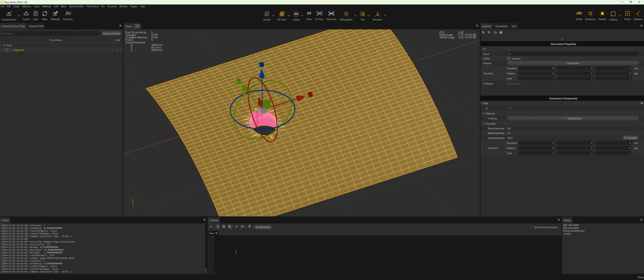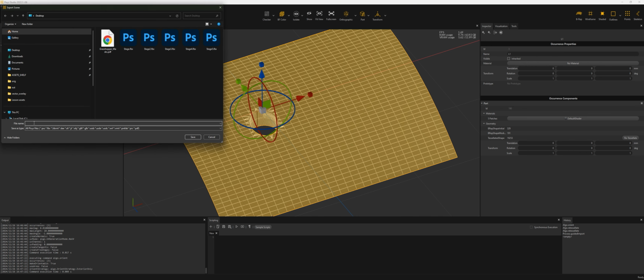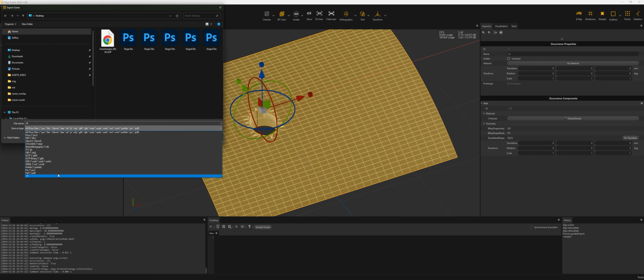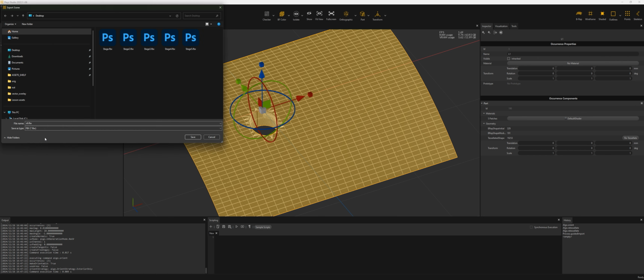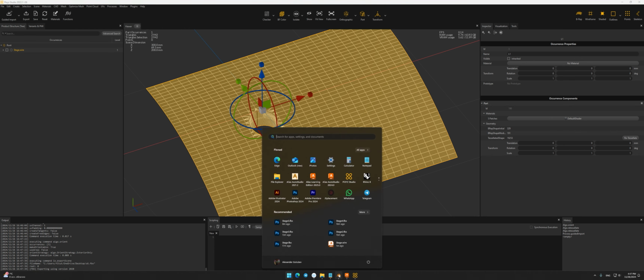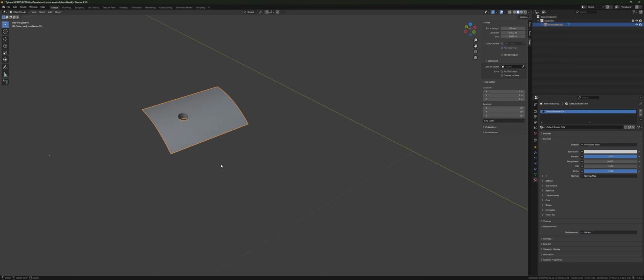Now, when we're done, first of all, I'm going to see that my normals are wrong. So let me just go to the mesh and I will say orient faces and execute. Okay, now it's good. And I will export that as it was stage 5, let's call it S6. I think that's good enough. And I will switch that so it will be more uniform with the other examples to FBX. And I will save that. And then I will open it in Blender.